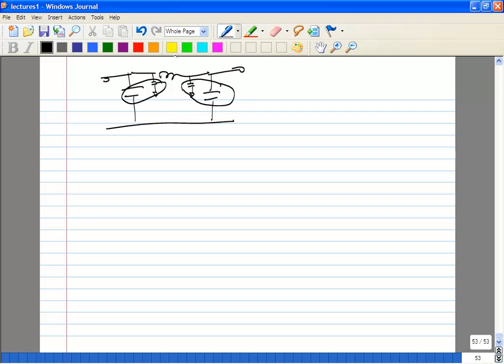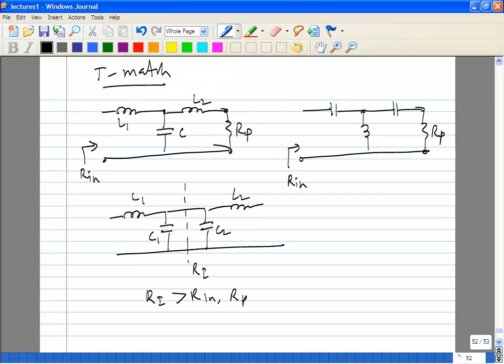And of course the other advantage is the matching network will not be sensitive because you have a large capacitance in parallel with the parasitics. It won't be very sensitive to the parasitics of the inductor. Similarly for this one, you have this parasitic coming in parallel with C, so you may end up preferring this one over this one in some cases. So it all depends on what is the value of the inductance, how much parasitic capacitance it has in parallel, how much area you can afford. So you'll have to trade off all these things when you are designing your circuit. Okay, is that clear?